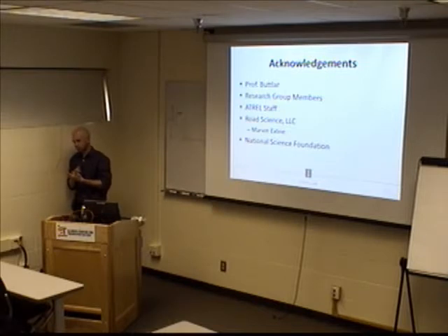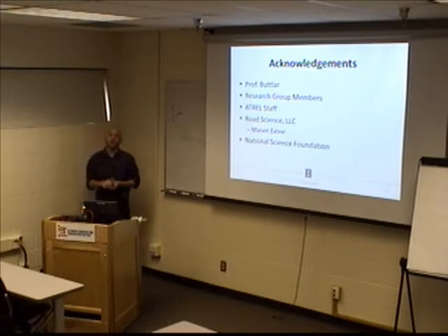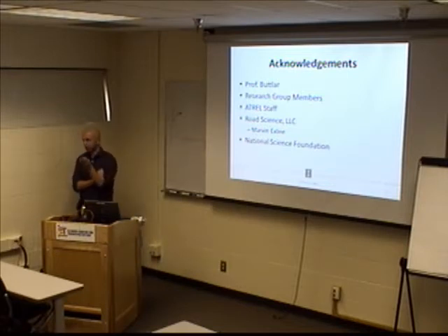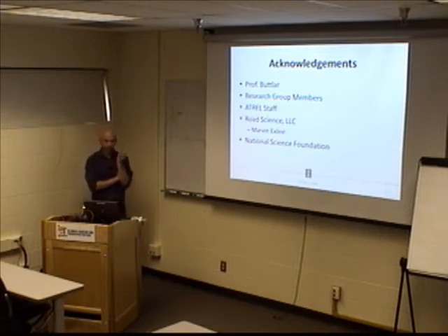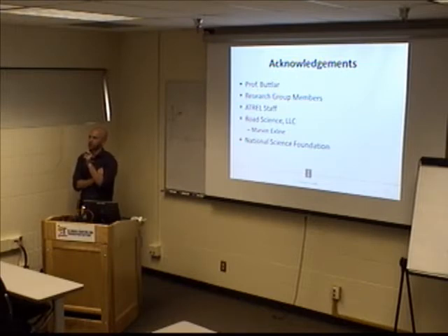Now, in terms of, you said calibration, right? Can you repeat your question? I want to make sure I answer it. The Delrin plastic test that we did. Sure. I didn't show any work that I did with Delrin plastic. Delrin plastic is very well known in terms of what its modulus is. It is a modulus very similar to asphalt materials. We went through and measured the Poisson's ratio and the amount of deformation that we'd have, such that we could back out what the modulus was. And we were probably within, I don't know, maybe, was it 3 to 5% maybe? Yeah, of the textbook value.